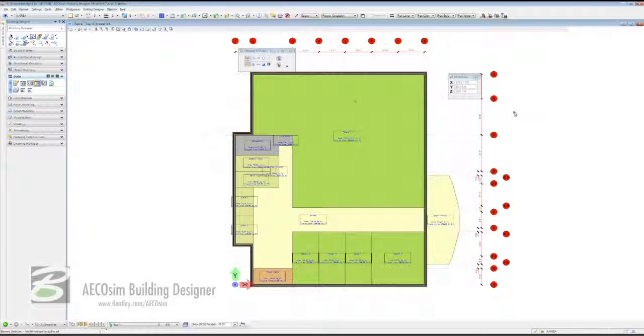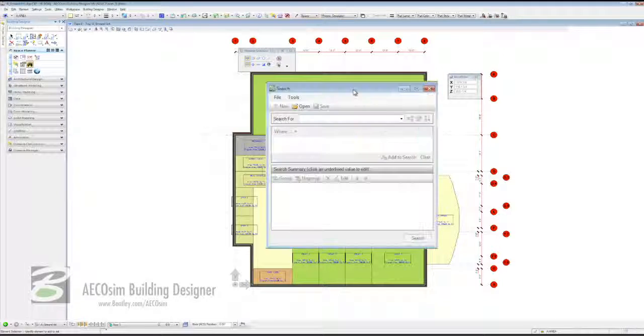We're going to close down Data Group Explorer now, and we're going to take spaces one more level, because we're going to come back to our task-based interface, to our Space Planner tab here. And in this, we're going to come 2nd row down, 3rd icon in, open the search dialog. The search dialog box opens up. It's made up of a number of elements, pull downs, icons, and fields. We just need to use the most simplistic side of it.